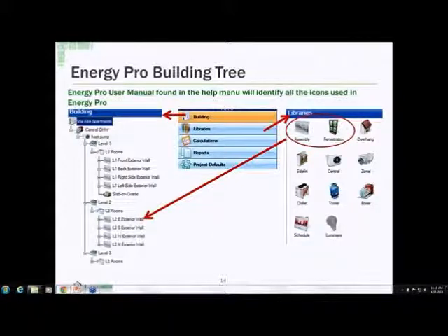So would you perform exhaust fan calculations on a low-rise rehab when sampling is involved? Yes, I would. I like to. I'm a real detailed person, so I like to get as much information about a building as possible. And if I can get information on the exhaust fans, I will include that. And there are ways of showing with the two-model approach how to get savings from the fans. You will get a baseline fan or test-in fan when you model it, and you can do another model, the two-model approach, and compare it to see what my fan energy use is for the improved building.